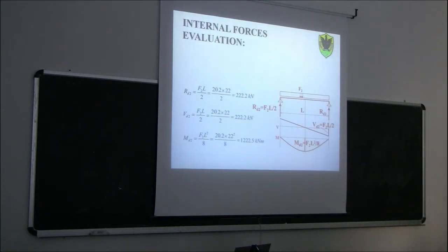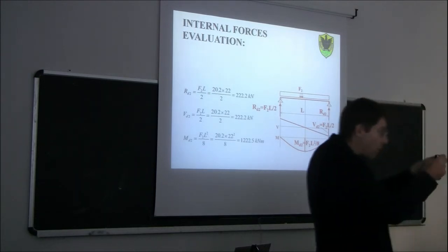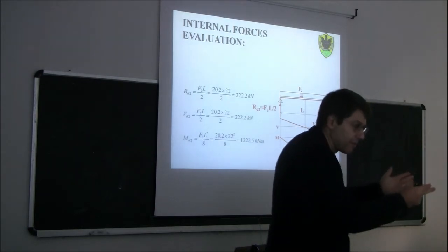So if you have an Excel spreadsheet, you can say, okay, I'm going to do the check on this preliminary size. I'm going to calculate the stress at the most stressed point, so the outermost fiber, to compare this stress with the strength. And then, if the verification is satisfied, more or less on the limit, okay, I finished.